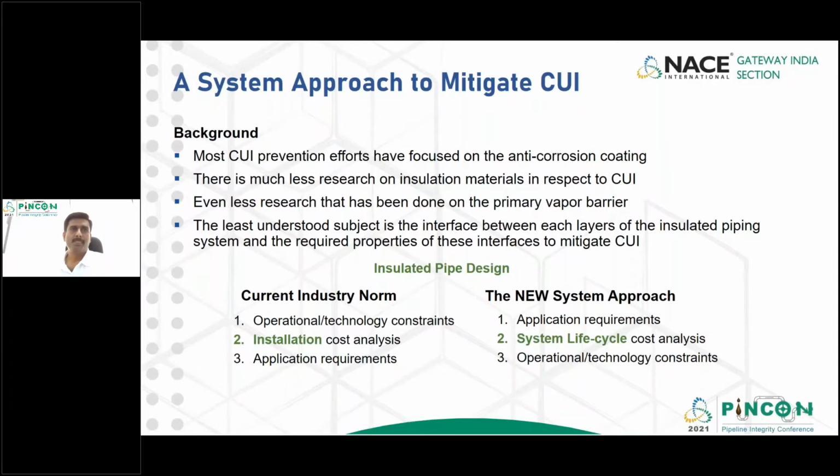The current insulated piping design norms are focused on the below hierarchy: operational and technological constraints, installation, cost analysis, application requirement. This design approach needs to be reversed to mitigate the corrosion under insulation.